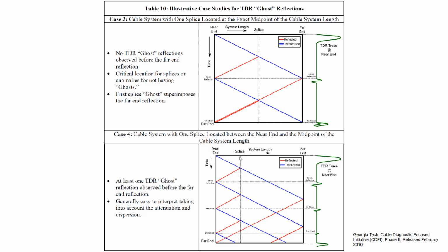Because the joint is located less than 50% of the distance, there is one reflection here, and due to that it again gets reflected here. You only observe a lesser magnitude here, and then again an even lesser magnitude further on. So the magnitudes are different, and there may be some dispersion and attenuation also. But this is the only joint. These two are not joints. These two are called ghost reflections.